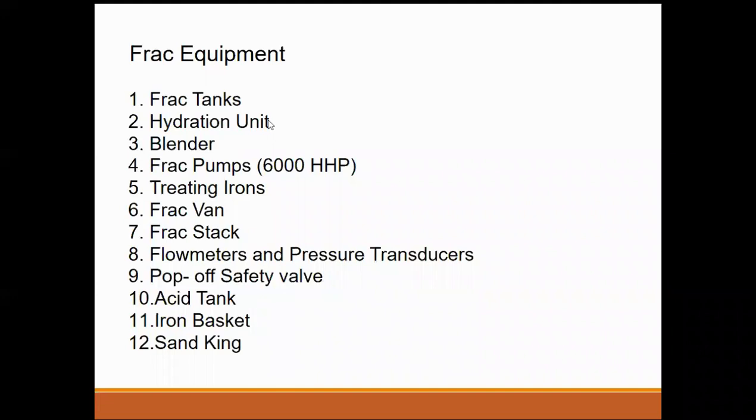Then there is the blender. The function of the blender, as I also told you before, is to mix the frac fluid and the proppant sand together so that they can further be pumped into the well. There are frac pumps. This is just an example, 6000 hp. The pumps need a certain hydraulic horsepower, and the requirement will depend on what kind of formation you're dealing with, what kind of fractures you want to create, and what kind of pressures you are expecting in your well while fracturing. So you'll select your pumps accordingly. I'll briefly touch on that point also.